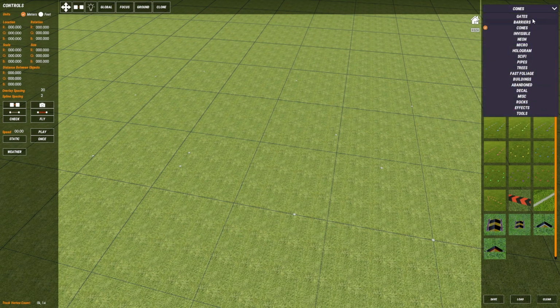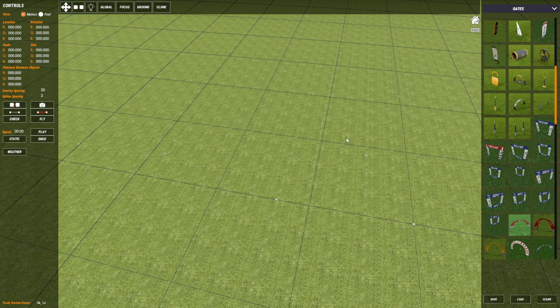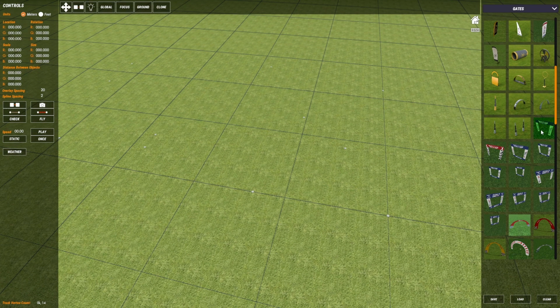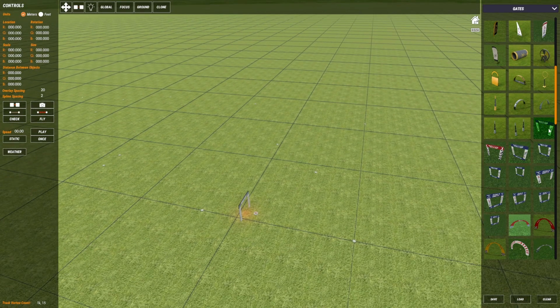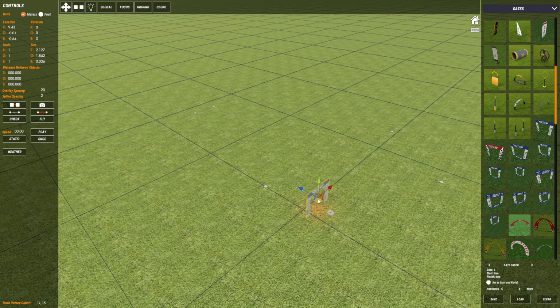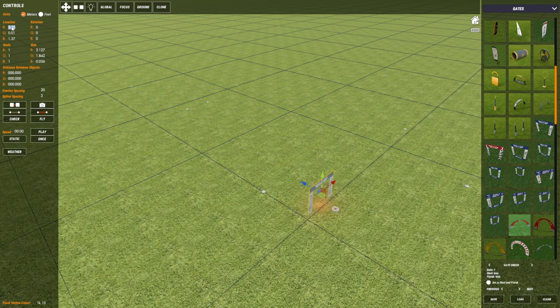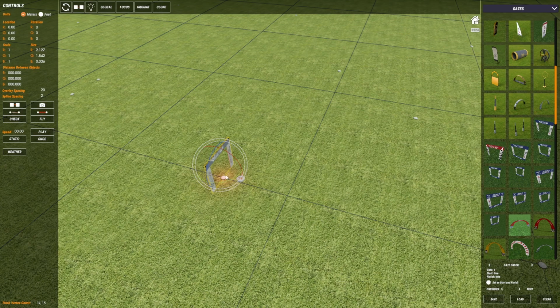We are going to start laying out the gates. So these multi-GP global qualifier style tracks use the 1.5 meter gates, or 5 foot gates. So that's the first one up here. And what I can do to accurately place these gates on top of the cones is I click on a cone and I press Shift Z. What that'll do is move the origin to the cone I selected, and then all I have to do is select the gate and zero out its location.